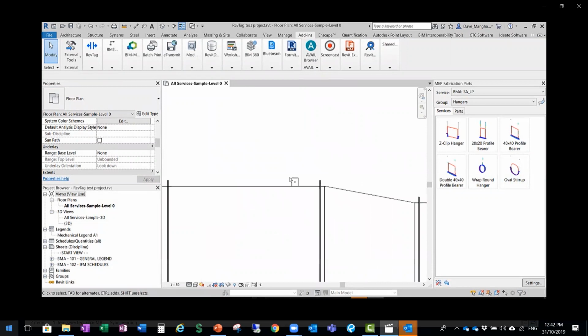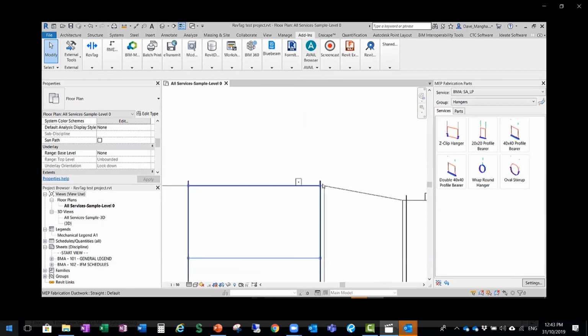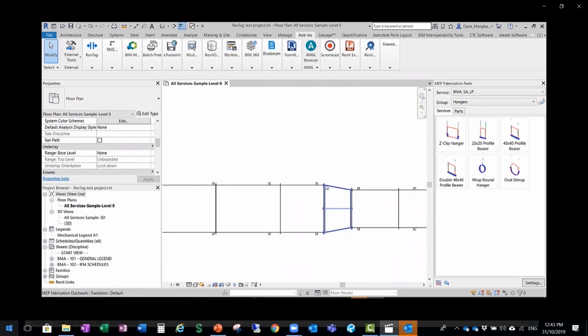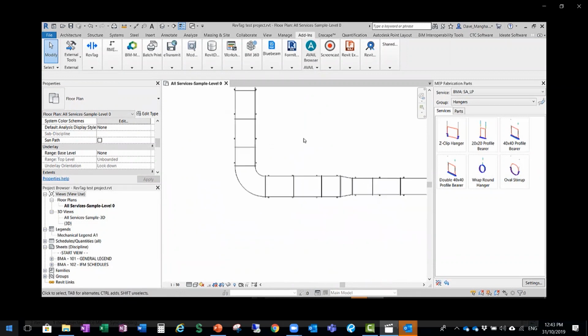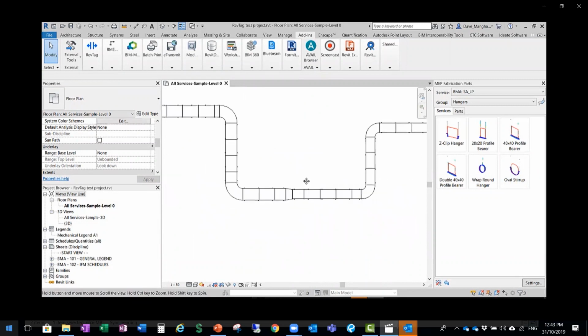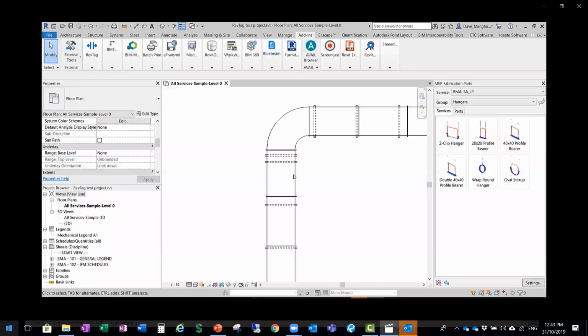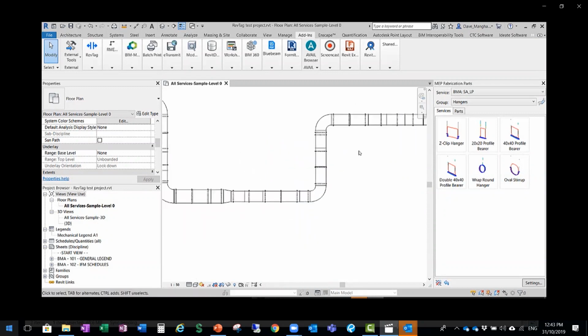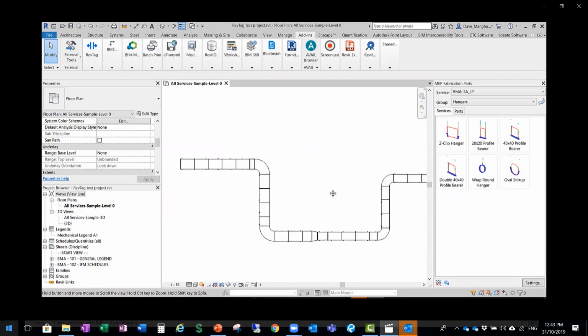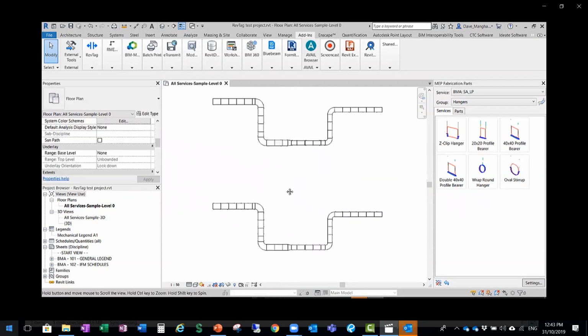We deliberately hard-coded it to prevent it from encroaching within 150 mil of a connector. That's why you've got this odd pitch here, in case you're wondering. Obviously, you've got freedom to move these hangers to wherever you so wish, and you will get instances where it's got a pitch there, and then it's got a gap over the 150 available, so it has put one more in there. Again, unfortunately, we can't control that at the moment. Maybe that's down the track. We'll look into doing that.